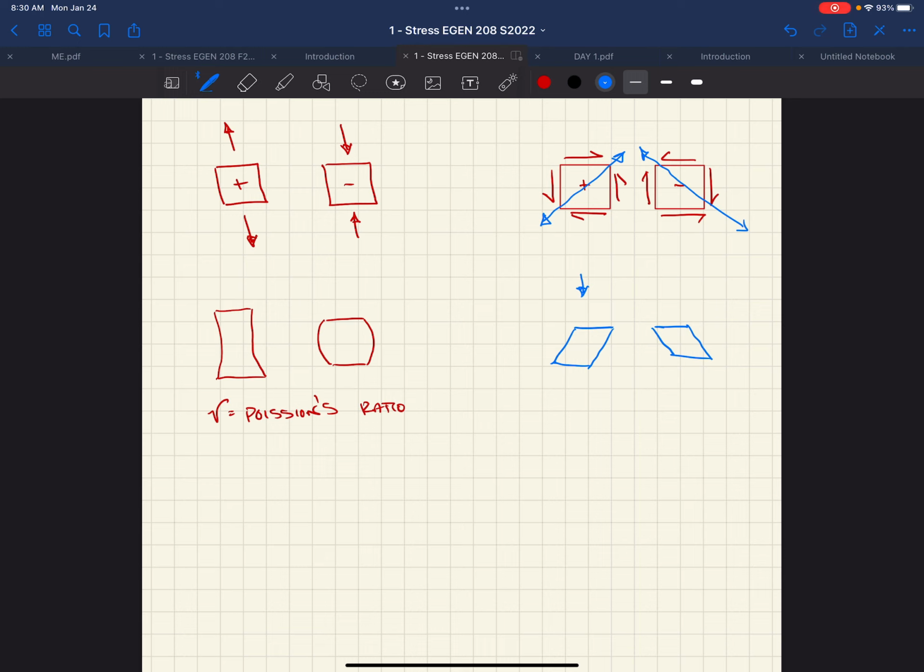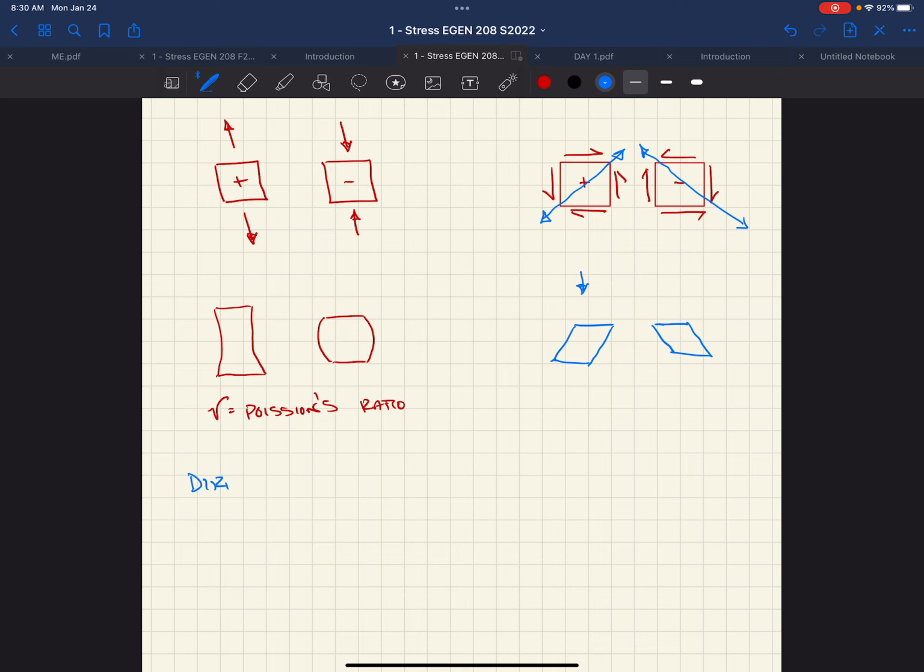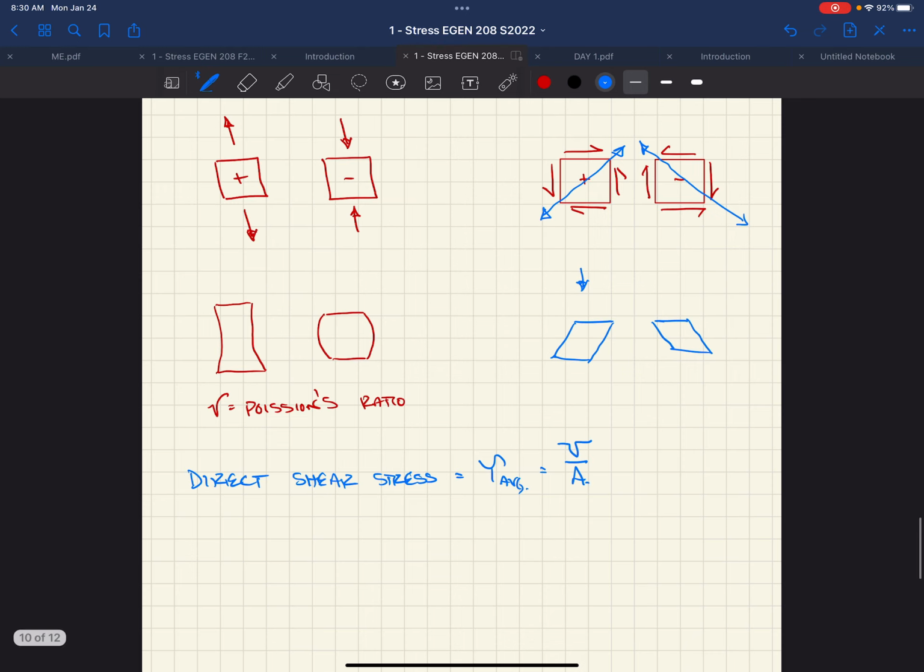Well, what does this equation look like? We know stress is force over an area. It's a pressure, so we have pounds per square inch. The force that we're going to be dealing with when we're looking for the direct shear stress, again, we're going to be calculating an average stress like we did with normal stress. In this case, it's denoted as V over A sub V, or our shear force, which we would call V, over our surface area over which shear is distributed, or A sub V.